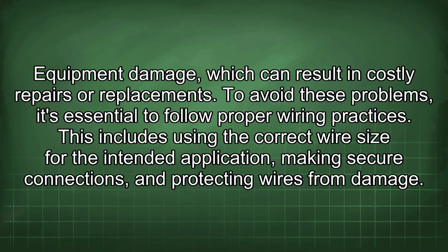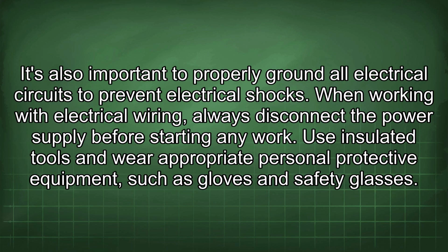To avoid these problems, it's essential to follow proper wiring practices. This includes using the correct wire size for the intended application, making secure connections, and protecting wires from damage. It's also important to properly ground all electrical circuits to prevent electrical shocks.